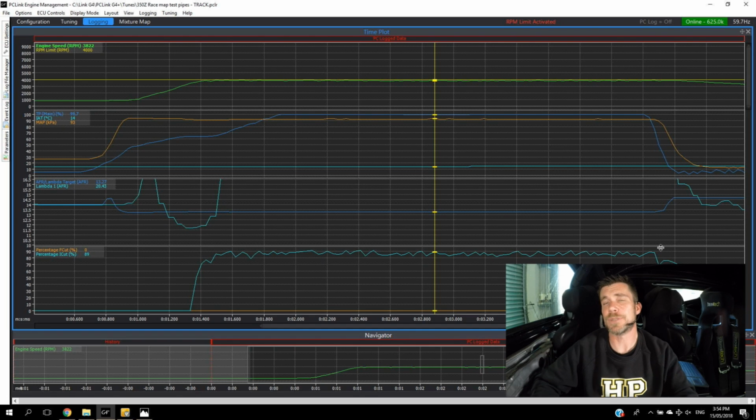If we're seeing large spikes, then the ECU is working harder to control that engine RPM, and that's likely to also show up in the RPM moving around a lot. The other thing you do need to be a little bit aware of here as well is the type of engine you're tuning, as this will have an influence on how smooth and accurate your RPM control can be.